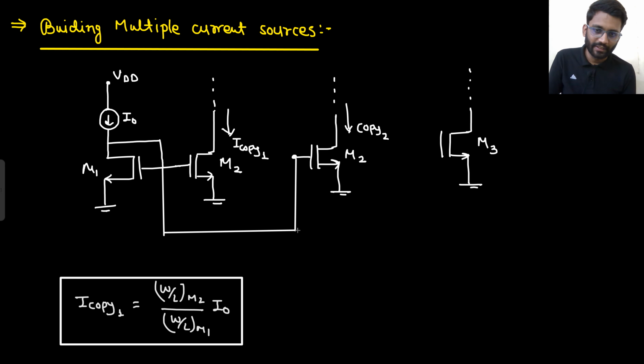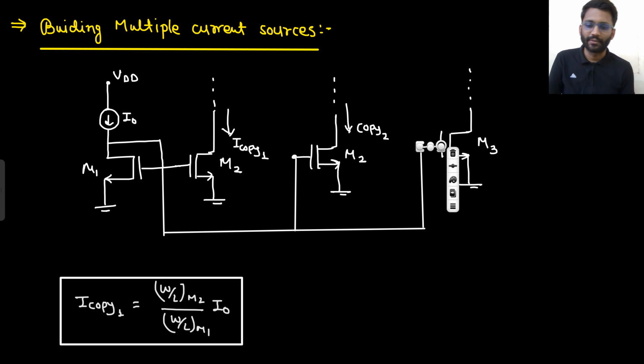The same voltage I am applying here as well. So I am giving the same bias to this one as well. Bias means DC voltage. If this has V potential, if the VGS value is V here, then this also has the VGS value V. Now this is 0, this is V. So V is traveling here and V will reach here. So basically, again the potential is V.